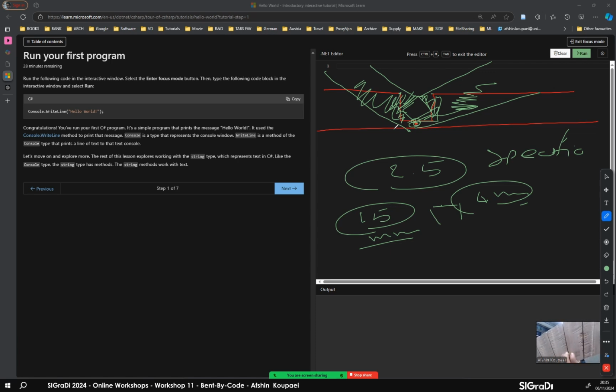So you see all of these creases are the situations that you are not going to have a good support of two pieces. So this is actually the not good piece, but it is following the geometry, but the parallel finish, if you see here, it's a 3-axis parallel finish. It's not a robotic parallel finish. Okay, I didn't find one of the robotic pieces to show you, but this is one of them.